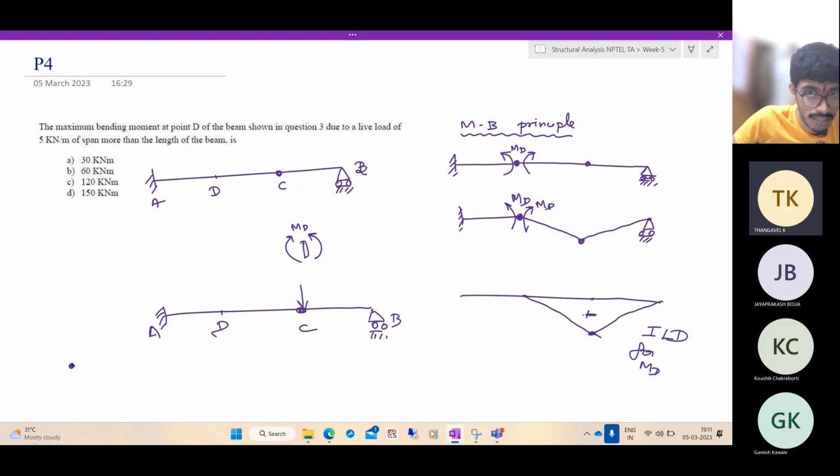On the hinge, this beam is connecting, RB equal to 0, which means this side there's no force, and this side there is some other force. On the hinge, the shear force that comes is something like this, and in addition you have the applied force of 1 kilonewton here. So this force is equal to 0, which means this force is equal to 1 kilonewton.